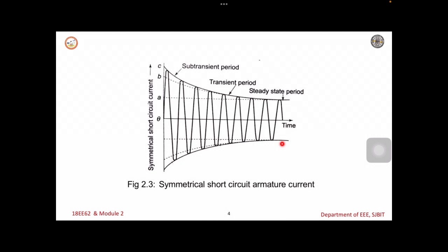The field structure rotates at synchronous speed along with the rotating magnetic field produced by the armature winding. During normal operation, the field produced by the armature currents is relatively stationary with respect to the field and damper windings. Hence, the rotating magnetic field will not induce any voltages and currents in the field and damper windings during normal operating conditions. That means, under steady state conditions, this is what happens.